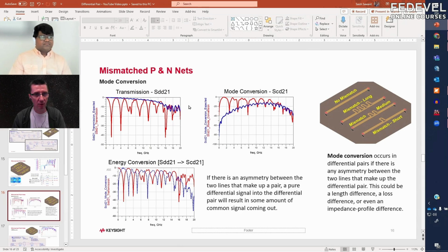So a good practice is to do a pre-layout study of what an ideal via is, how to design the vias, how the return vias should be around it, and all of that. Once the via is optimized, they can replicate that via geometry whenever they are making these transitions.